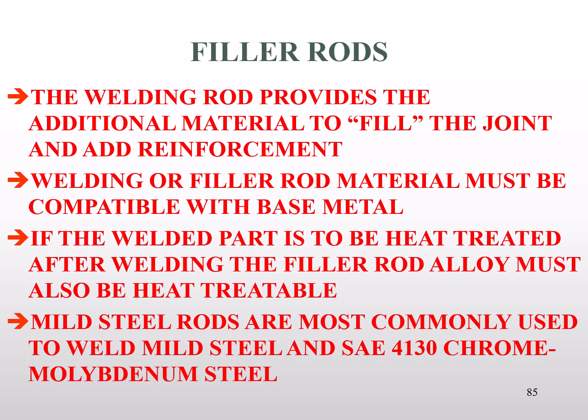Let's discuss filler rods a little bit. Why do we need a filler rod? A good weld, if you look at the required dimensions, will be thicker than the material that's joining it. So where are we going to get this extra material from to make the weld thicker than the base material? Well, that's going to come from some sort of filler. In gas welding, we use filler rods.